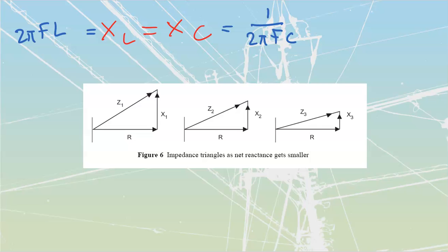And so what we would see out of these two formulas is that as my frequency increases, if I add frequency to a circuit, that frequency is going to be seen by both the capacitor and the inductor. As the frequency goes up, my denominator goes up, which means that my XC would be going down. If that frequency is going up, my XL would be going up. So I'm going to have an XL that's rising while my XC is dropping. And eventually, we're going to hit a point where both of these are going to be exactly equal.